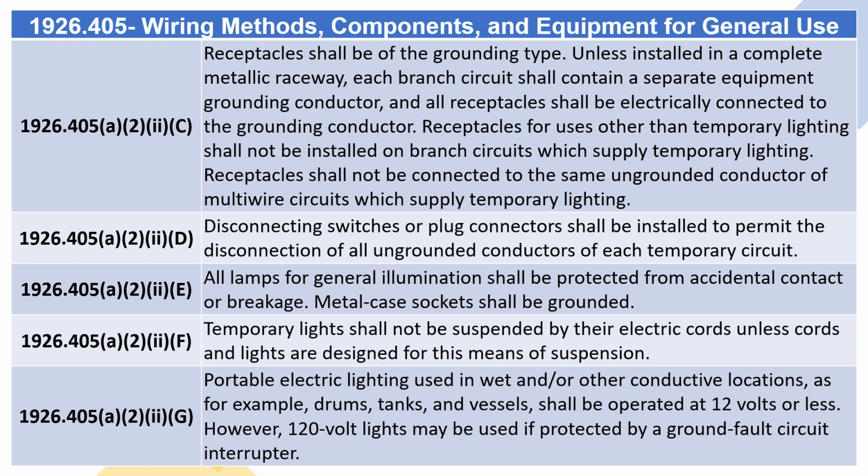All lamps for general illumination shall be protected from accidental contact or breakage. Metal case sockets shall be grounded. Temporary lights shall not be suspended by their electric cords unless cords and lights are designed for this means of suspension.